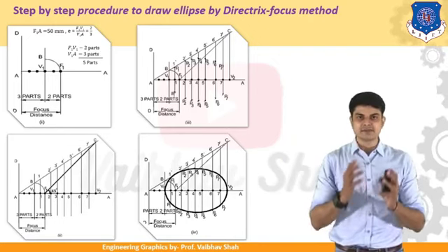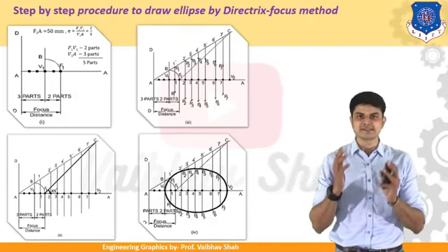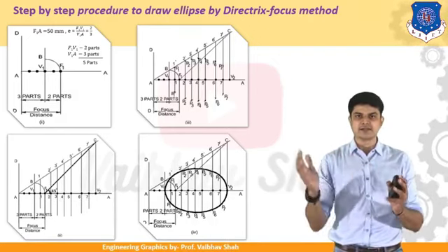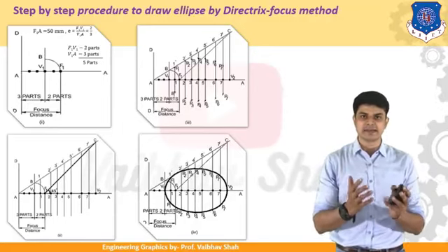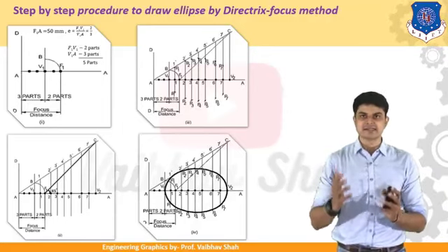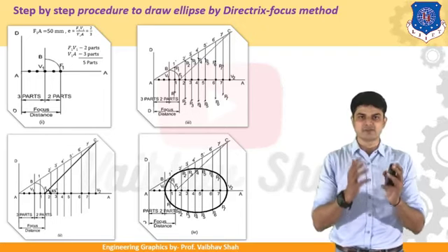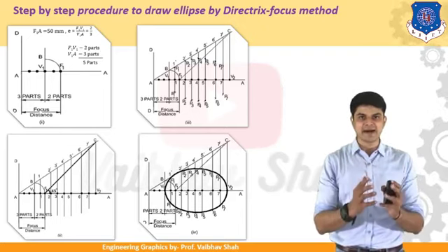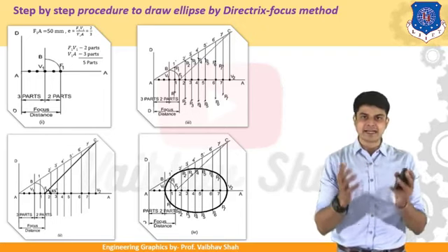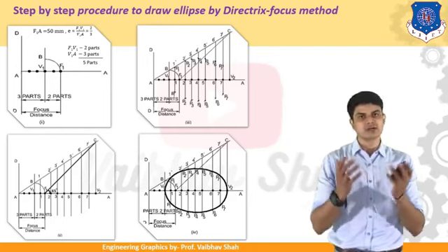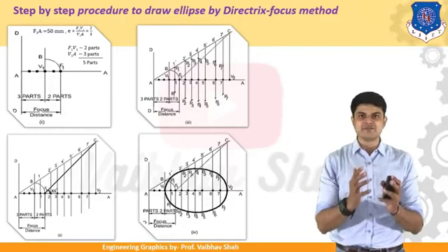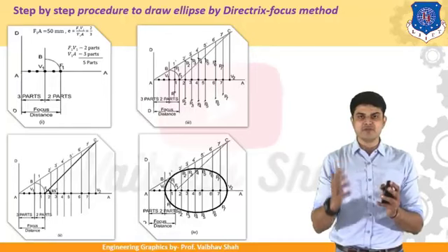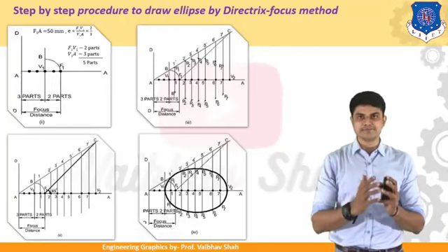Then after, it is automatic that if the 20 mm distance is between F1 V1, then another distance would be obviously 30 mm. So which is our required answer, which is the distance of V1A, which is equal to 3 parts, and the single part dimension is 10 mm. That means V1A distance must be your 30 mm. So we have identified the points F1, V1 and A on this horizontal line.